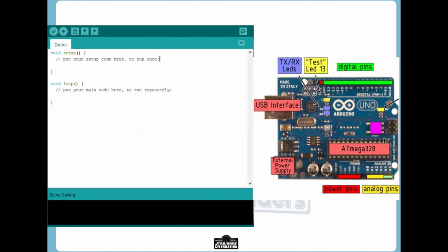Once you plug it in, you'll get the option of connecting to it by choosing the Arduino Uno, if that's what you're using, and you'll be able to then compile software and upload it to your actual board. It's important to note, once you write software and push it to the Arduino, it'll just start working. So you can't retrieve that code back. Whatever you push to it, that's the latest code that's going to be on there. Okay. So we've plugged it in, we've got it connected, we're ready to rock and roll.